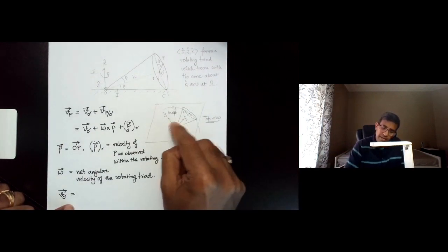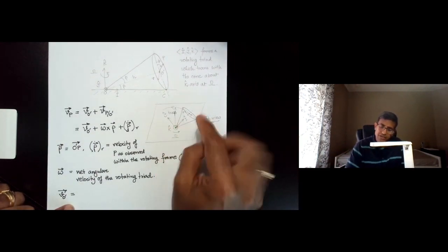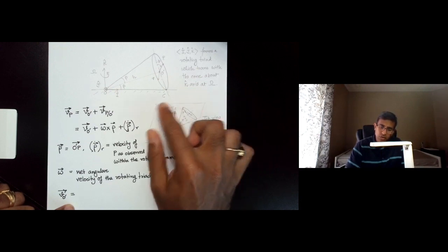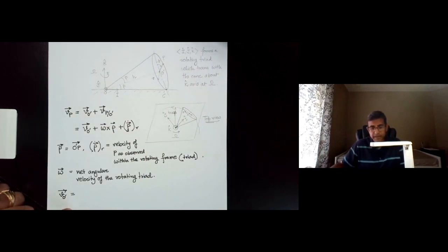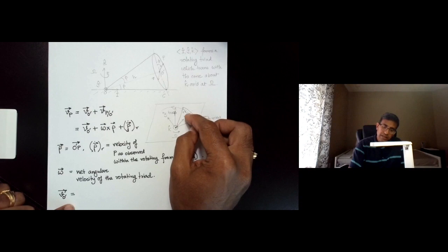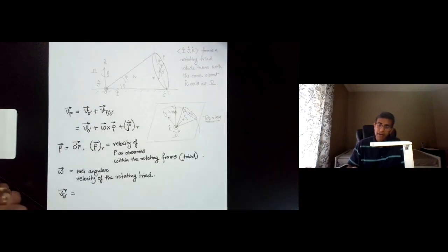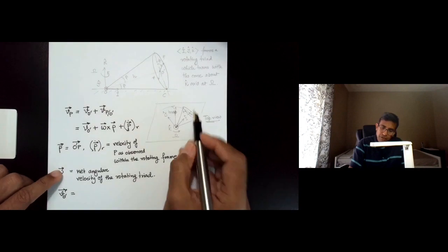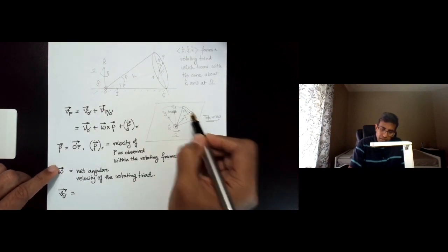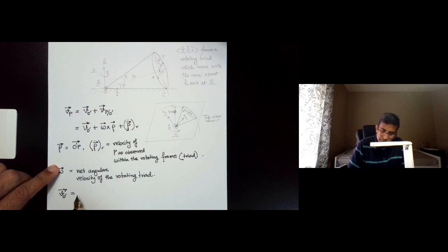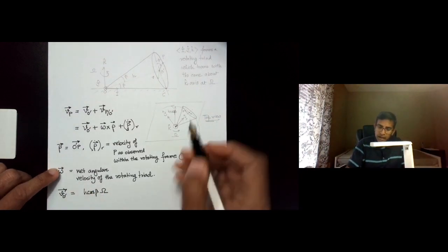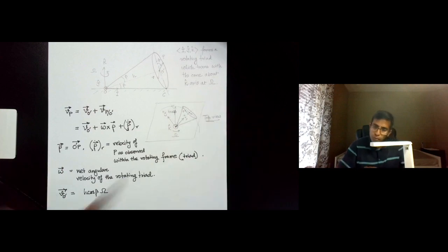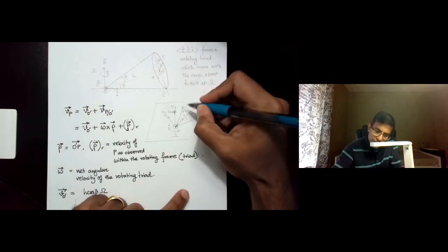and the angular velocity with which the point O prime is going around is this omega. Okay, omega is the angular velocity with which this point O prime is going around in this horizontal circle. So therefore the velocity of the point O prime is going to be H cosine beta times omega. And if you think of the direction, the velocity of O prime is going to be tangential to this circle at any point.